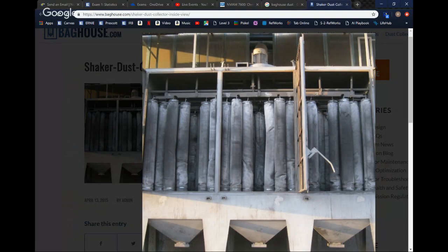That's another combustible dust issue. What if your ventilation system captures a spark that stays live until it comes in here? That's not a good thing. So one thing you can do is have a spark arrestor that will prevent them from reaching here. I don't know exactly how they work, but another option is to make sure this is outside of the building.